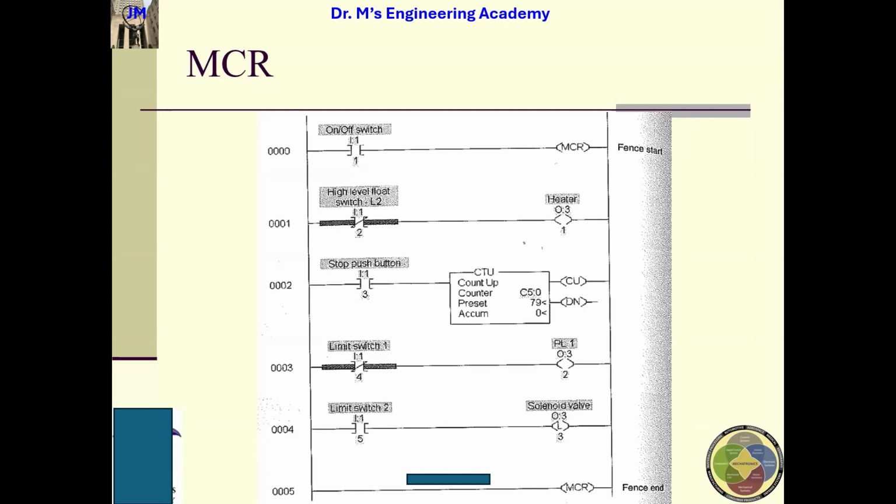Also, at the same time, you cannot control this counter. This counter will not be triggered. However, for this guy, because this is retentive, if this guy is turned off, this guy will still latch. No matter what you do, that guy still latches.